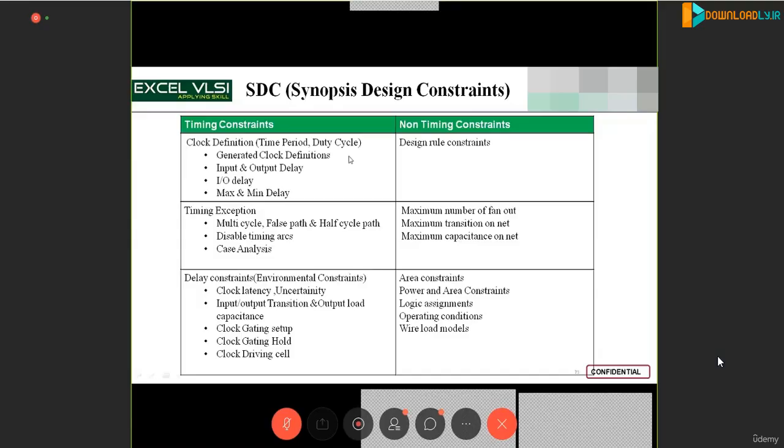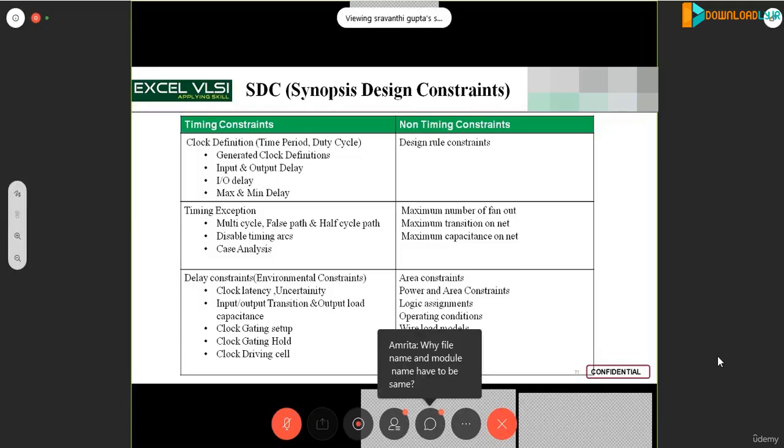So you can ask me a question like this: the delay values of the cell pins are there in the library, but the port objects, whatever you declare in RTL as input pins and output pins, those port delay values we are not defining anywhere in the library. So those delay values we are writing in this particular file called the SDC file. Next are some timing exceptions. So these are all the optimization constraints.